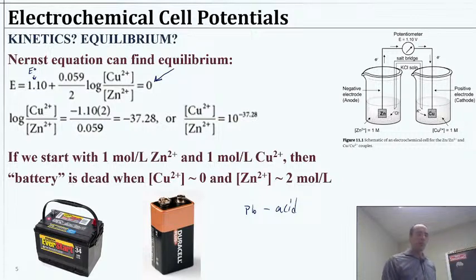and theoretically they shouldn't if we could go back and forth in these phases, no problem. Well, there is a bit of a problem if there's some loss of water. It actually turns out to be one of the major problems. So technically, you can preserve these batteries a lot longer and better if you occasionally maintain them by adding some DI water to the cell appropriately. And a lot of them do have a port for that.